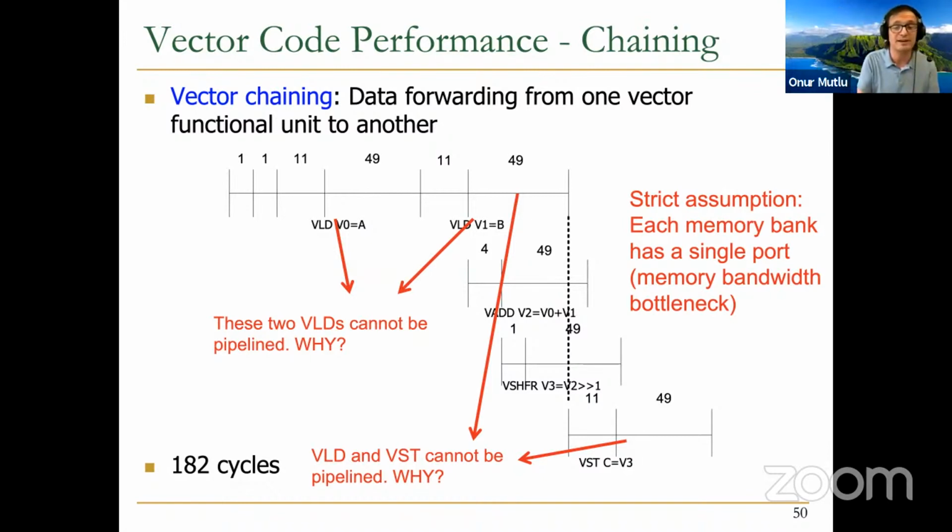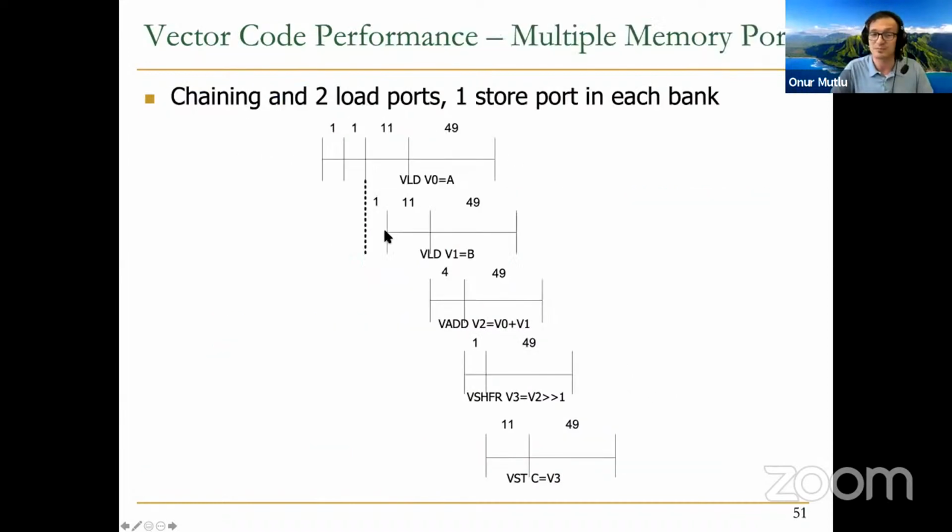This is very similar to the register file that we saw, the multi-ported register file, right? You can have multiple ported register files so that you can access source register 1 and source register 2 concurrently. That's what we're trying to do over here. We want to access A and B in different locations. So A and B are the banks here, right? No, A and B are the vectors. Banks are 16. We have 16 banks.